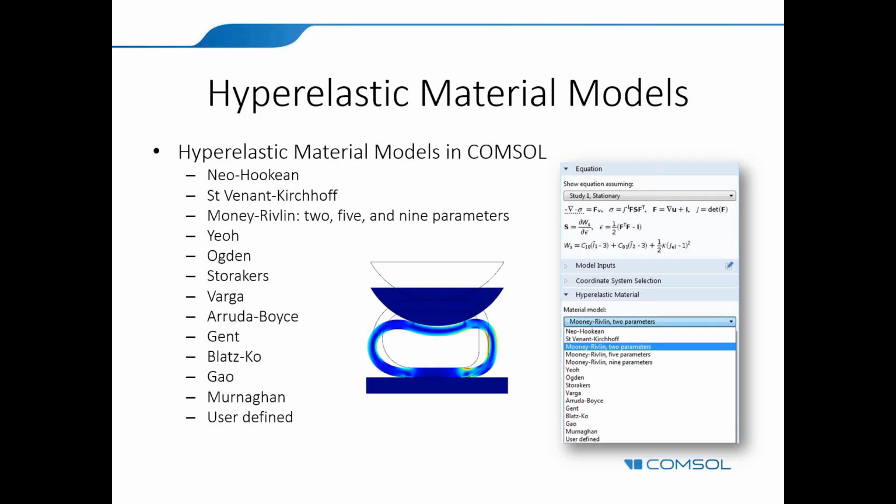Geometric nonlinearity is basically associated with the concept called large deformation. What it really means is, usually if you read a standard undergraduate level textbook, for example, you will see the strain definitions are linear with respect to the displacements. They are proportional to the displacement gradient raised to the order 1. But that is not true in reality whenever you have large deformations, as is the case in hyperelastic materials, where you have large deformation and large strain.